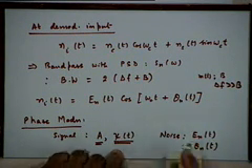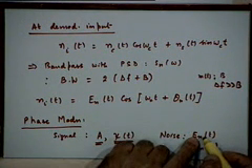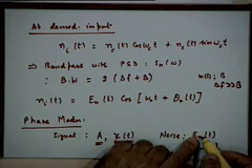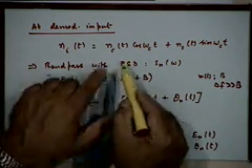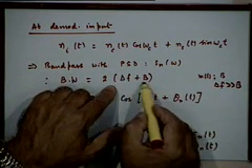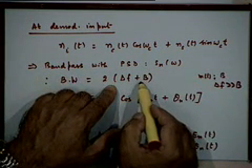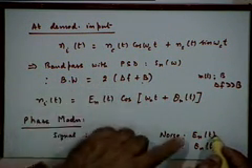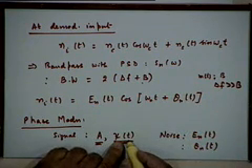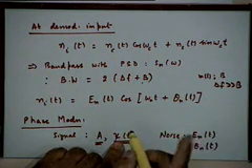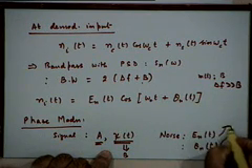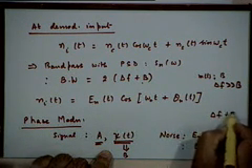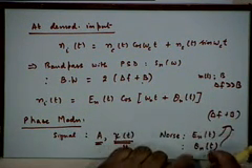Now what we are saying is that e_n(t), the instantaneous amplitude of noise, and theta_n(t) will have a bandwidth proportional to delta F plus B. So they will vary much more rapidly than psi of t. This is the important point. Psi of t has a bandwidth of B, and each of these has a bandwidth of delta F plus B. These are low pass signals.